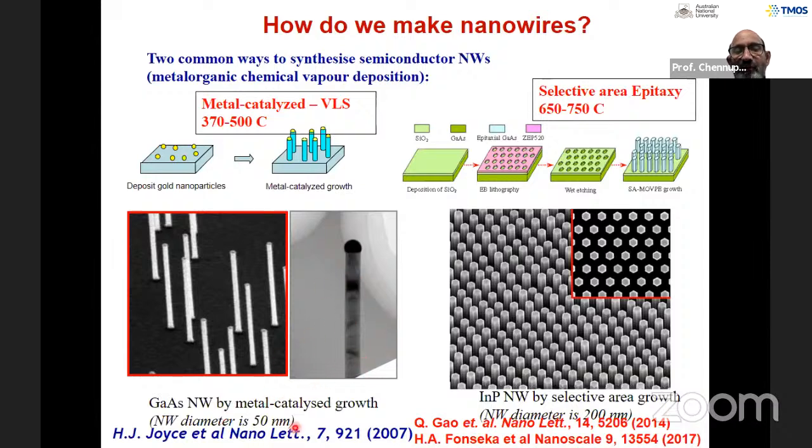So these nanowires are about 50 nanometers in diameter, and essentially you can change the diameter of the nanowire by changing the nanoparticle diameter. And we have demonstrated nanowires as small as 10 nanometers, as big as 300 nanometers using this particular process. And also we've demonstrated lots of other materials using this VLS growth process, because we are incorporating a vapor into a liquid and getting a solid.